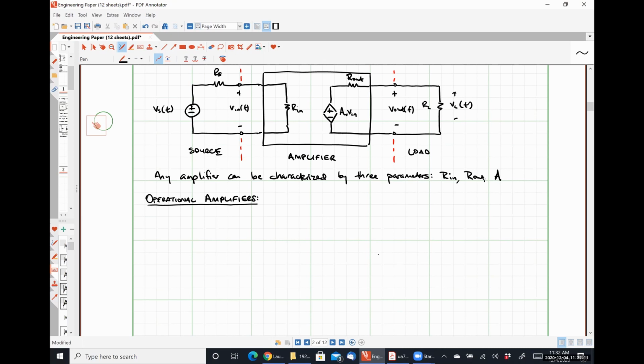The reason is that an operational amplifier is what's known as a differential amplifier, meaning it doesn't amplify a single input signal, it amplifies the difference between two input signals. That's why op-amps have a non-inverting and an inverting input terminal. What's actually being amplified is the differential signal.